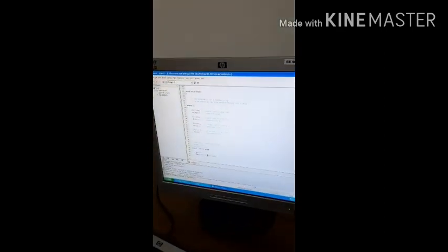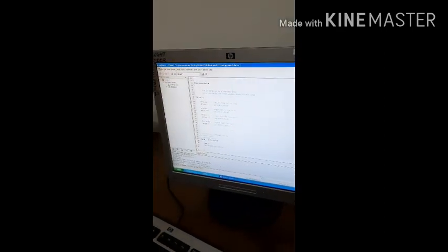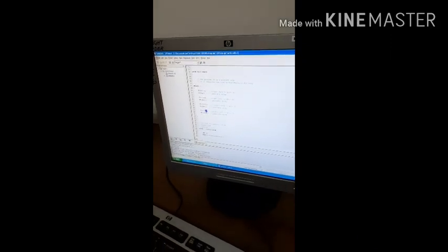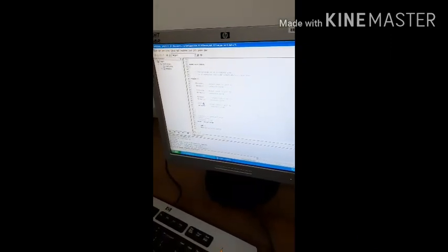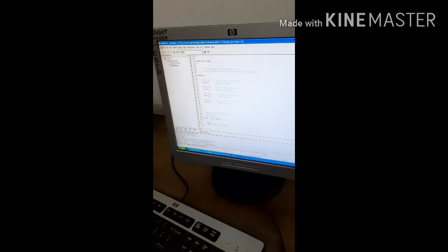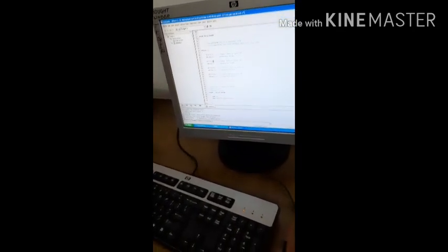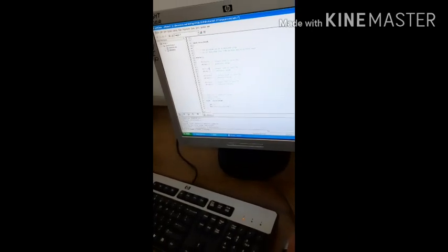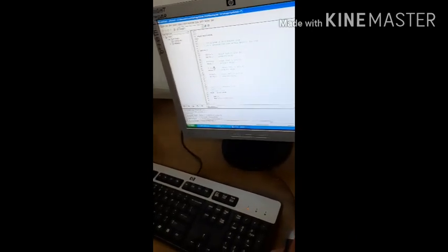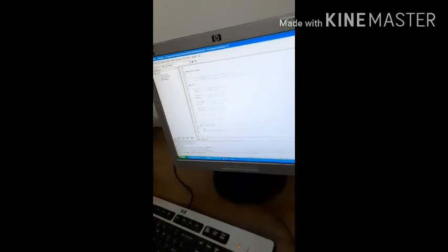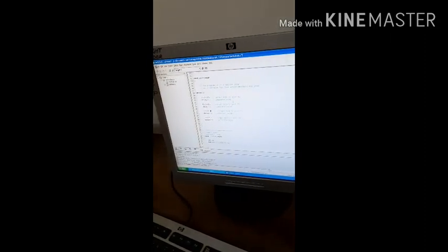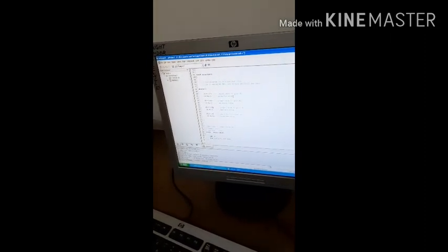So now this 0E should come here and 07 should go there. This is 0E. This should be 07. Now these two you interchange. This is B and this is going to be D. I have simply interchanged the codes here, right? So these are the codes which are going to your microcontroller.